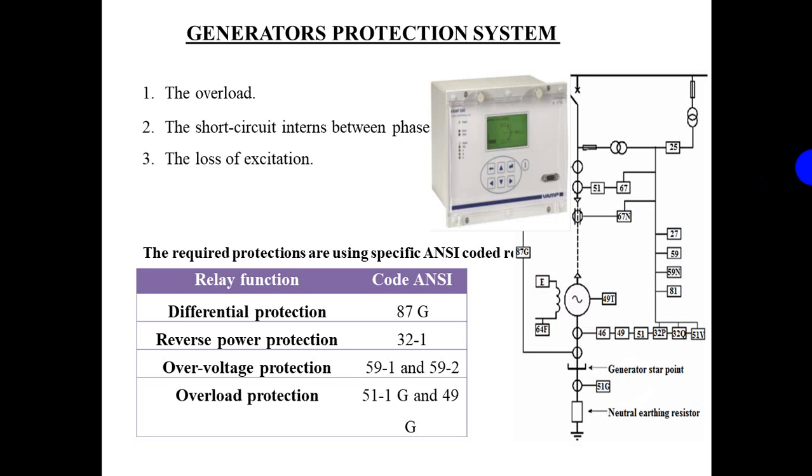This type of protection was considered unnecessary in previous days because breakdown of insulation between points in the same phase winding contained in the same slot, and between which the potential difference exists, very rapidly changes into an earth fault, and then it's detected by either the stator differential protection or the stator earth fault protection.